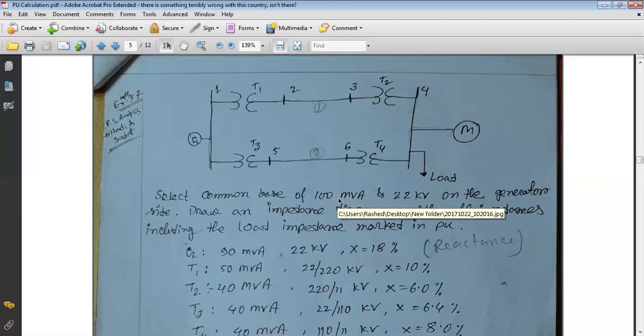So we can say the generation side is connected through bus 1. The connection between bus 2 and bus 3 is high voltage transmission line 1. The connection between bus 5 and bus 6 is high voltage transmission line 2. And bus 4 is the distribution side connection, where the loads are connected through the lower voltage portion of the double circuit parallel transmission line.